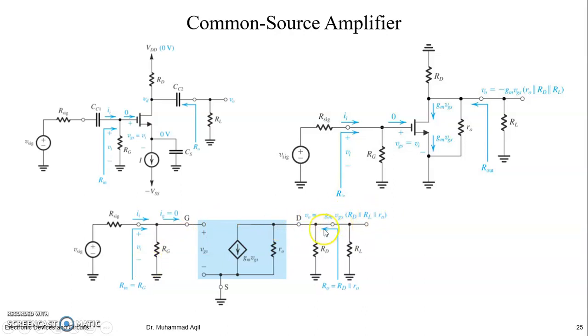When you put V in here, put it down, this is your gain, right? AV or AV not? It's AV because you have considered RL. If you remove RL, then it is AV not, right? And now if you put VGS equal to V in, and V in equal to V signal times RG divided by RG plus R signal, then you introduce the V signal, and when you put the V signal down, you actually find the GV.